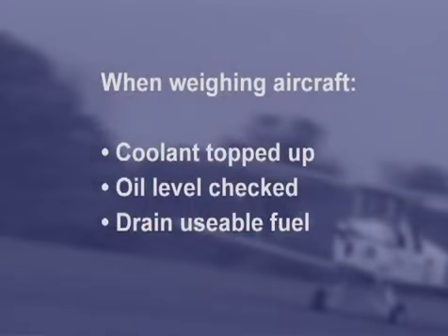When you weigh the aircraft, check, for instance, if you have something that's liquid cooled, so you make sure your liquid coolant is topped up, your oil is at the level it's supposed to be. You want to drain all the fuel out so you know where to start as far as using your weight and balance.